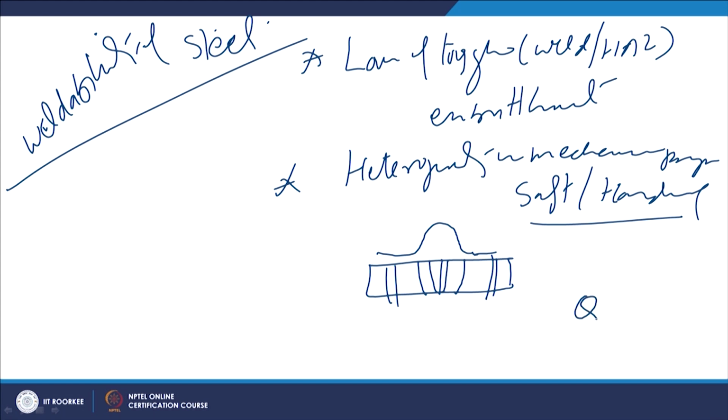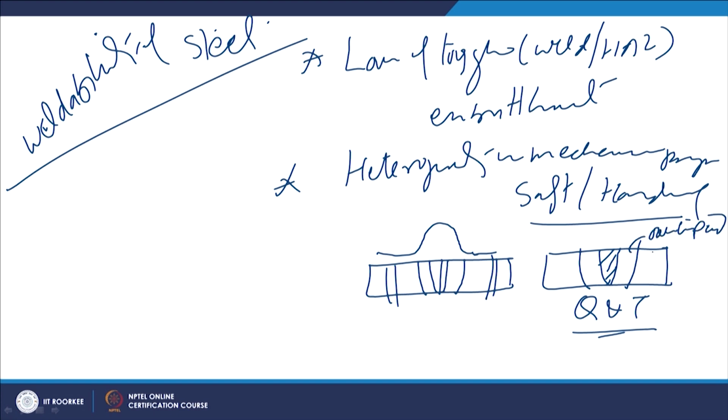But if the steel is in the QNT condition, then we will notice that due to the higher cooling rate during welding, the weld zone invariably experiences martensitic transformation, and so higher hardness, but the zone next to the weld metal is over tempered, and that is why this zone experiences the loss of hardness. So, the base metal has higher hardness, but as we approach the heat affected zone, hardness is reduced. Then in the weld metal again hardness is increased, then hardness is reduced.